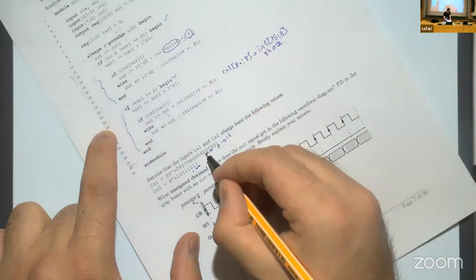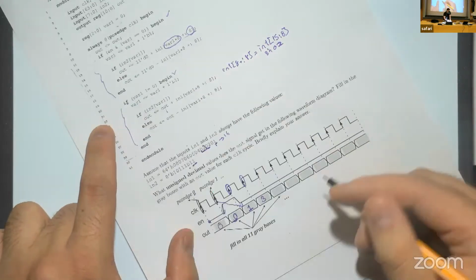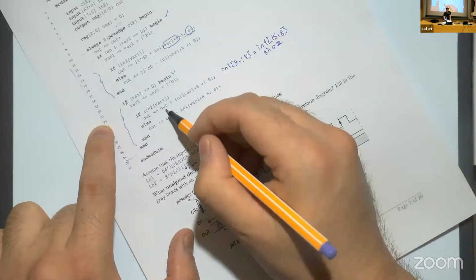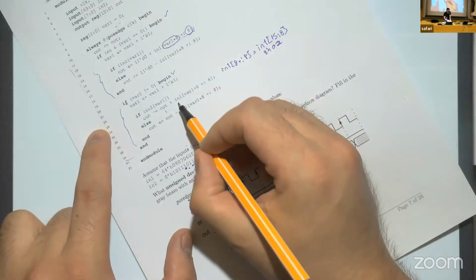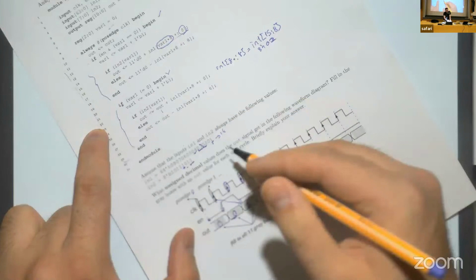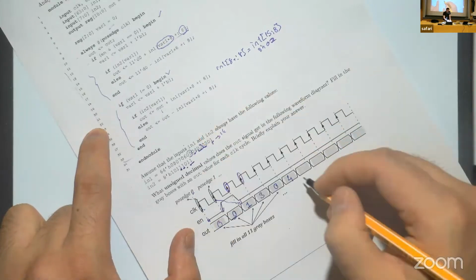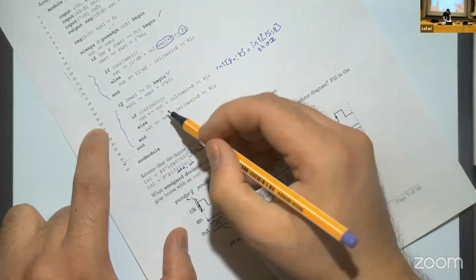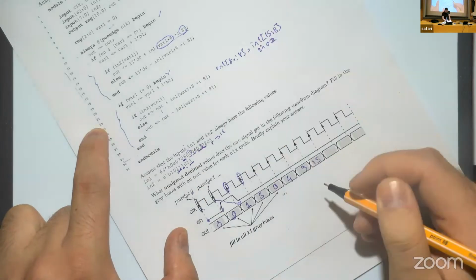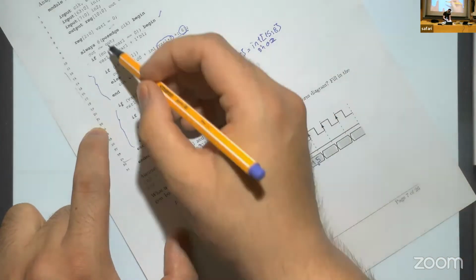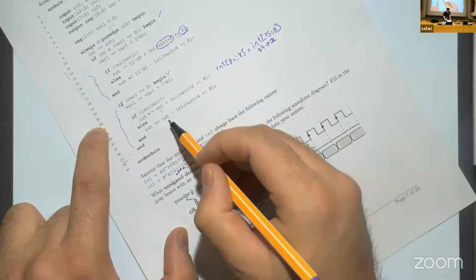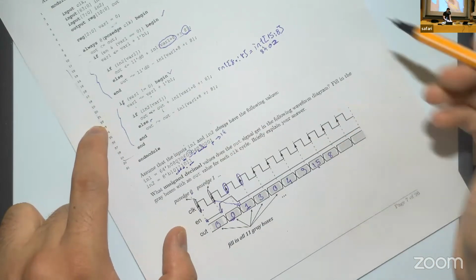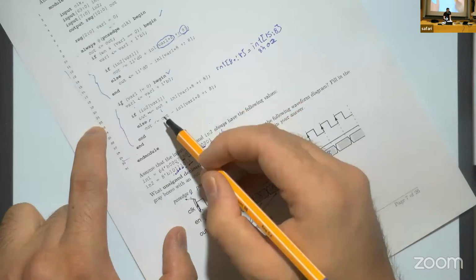Now in the next cycle, we execute again the always block where var 1 is now, I guess, 6, yes, which is 0 in the in2. Which means that we need to perform subtraction here. It was 15 and this one is 7, makes it 8, I guess. Yes. Okay. Now we perform the same thing again, where var 1 is 7. The 7th bit of in2 is 1, which means that we need to add.